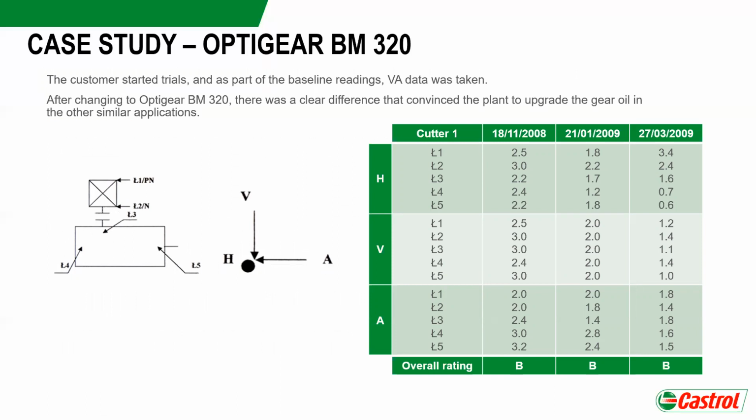So what it does is smooth out the surface, which means that you reduce the height of that surface roughness, so the film thickness is larger than the surface roughness. Once those peaks have been smoothed out, you end up with a larger contact surface area that the base oil itself is able to support and not let metal-to-metal contact occur. So what does that mean?